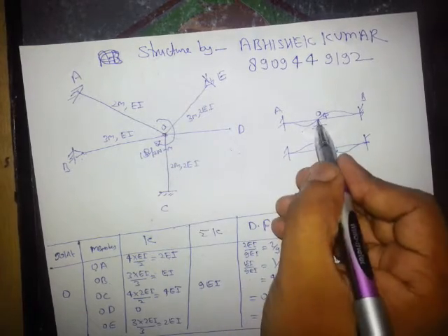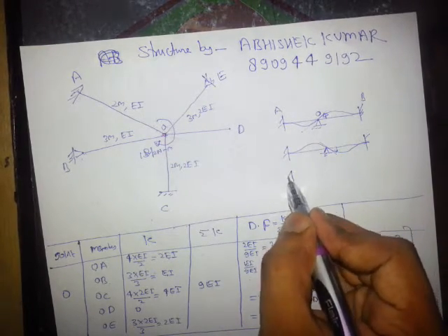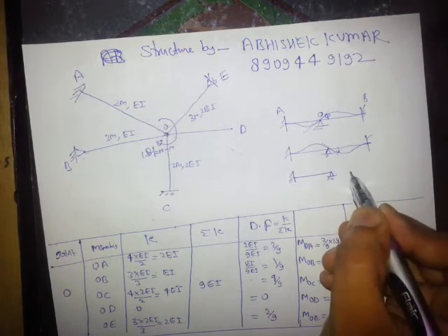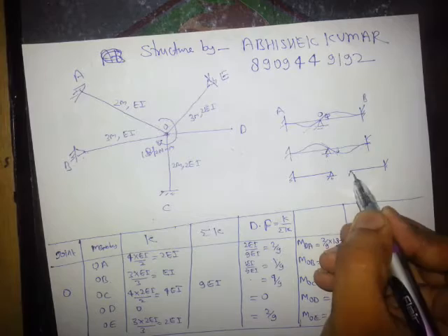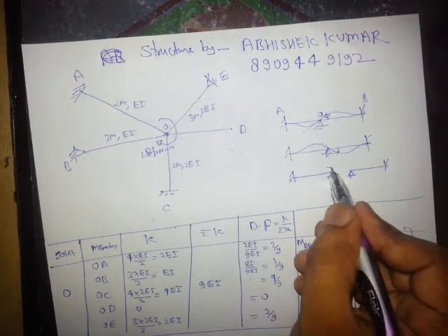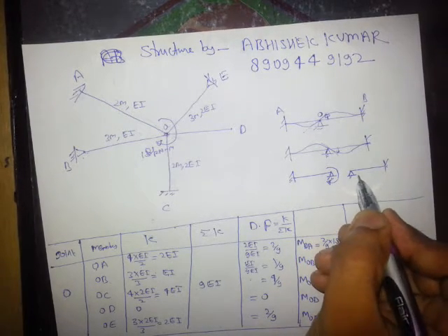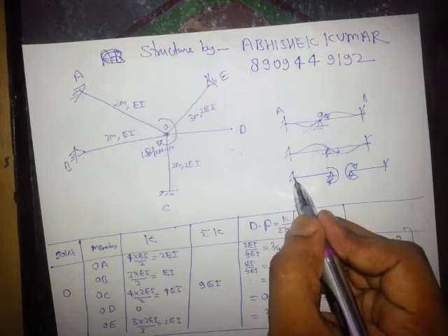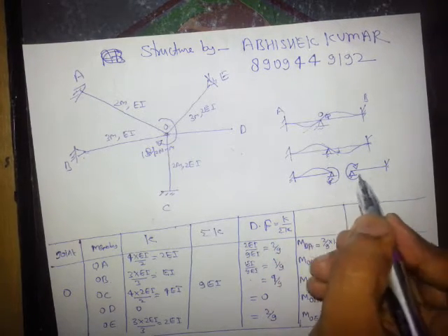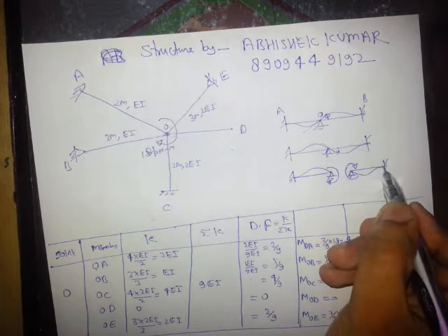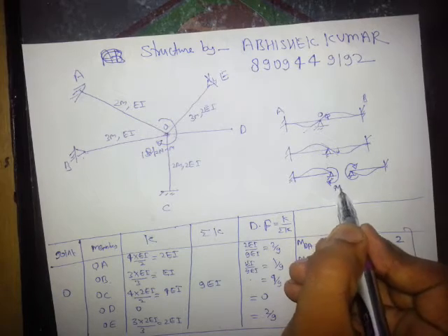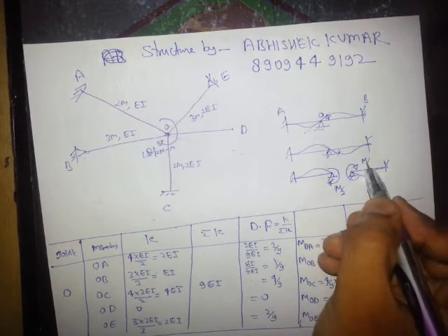So you can say that you can convert this to a hinge support and this to a hinge support. Due to the applied loading, we can calculate the moment. For example, these are the moments. So now we can calculate either this rotation or this, and if this M is known, for example this is M, this is M by 2, this is also M by 2.